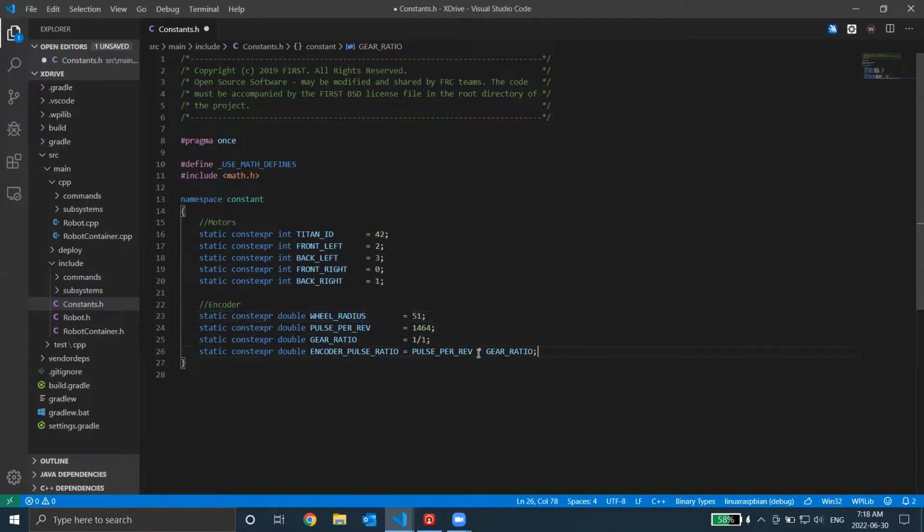So you can see here how we incorporate the gear ratio with the pulse per revolutions. If we had a 2-to-1 ratio, this value would have to be double what it currently is, so that we get a correct calculation. For example, our wheel would have to spin once, but our motor is actually spun twice, so the count is double. Or the opposite way, the count will lower if your motor spins only half, but your wheel is spun once.